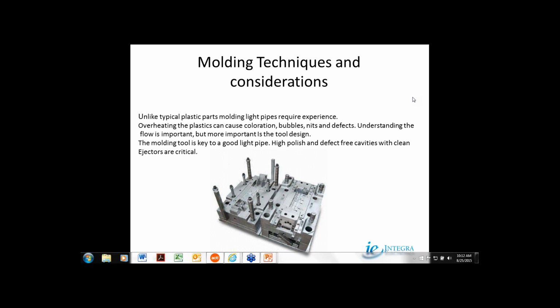Yeah, let me add a little bit to that. Typically, when we design a light pipe, we try to minimize any use of reflective paint just for the fact that it adds cost and expense to the process. The basic design principles that were laid out in a little bit more depth, if followed, actually reduce the chances of having to use reflective paint.